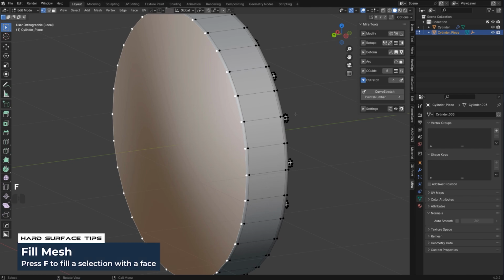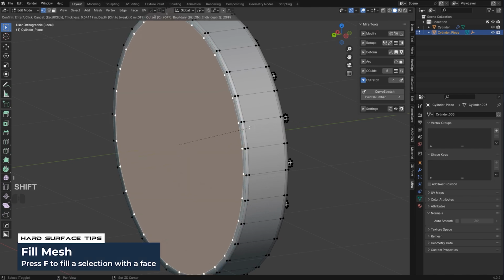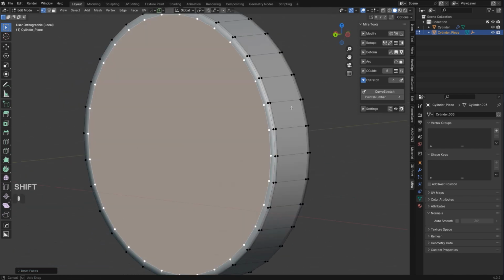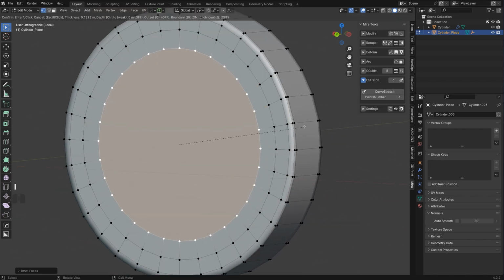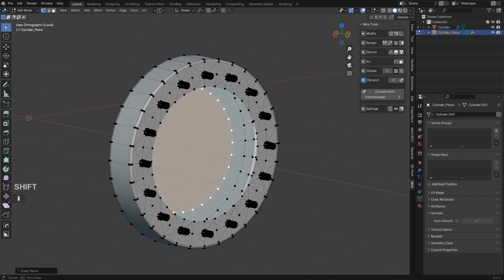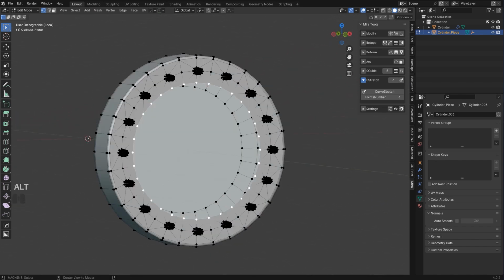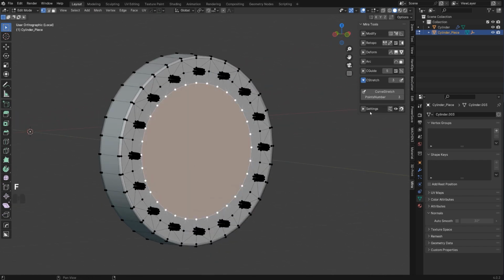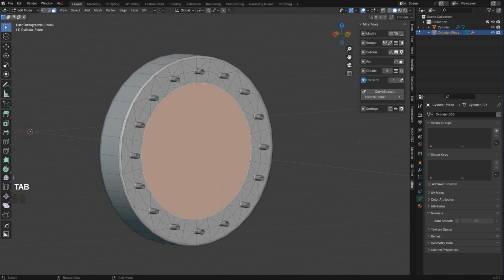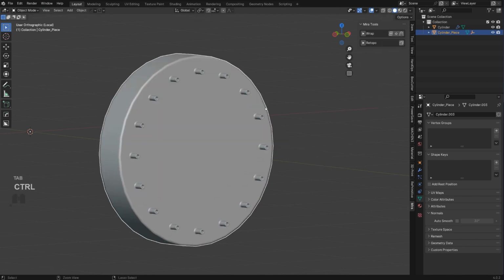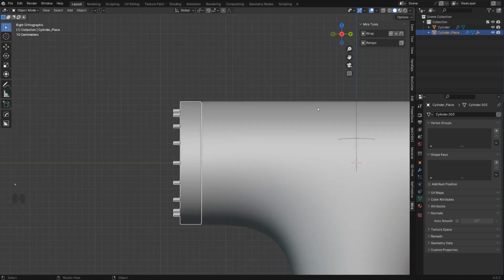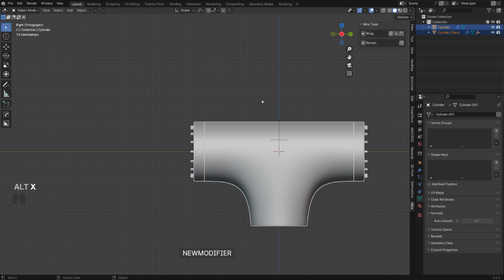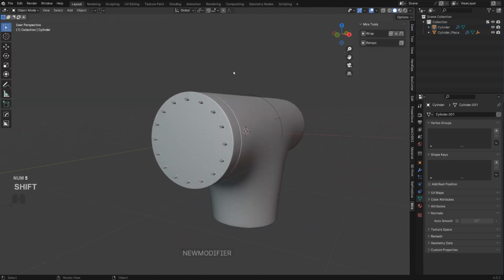So face, insert it just a little bit to create this kind of a really shallow bevel. Insert twice in here. We don't really need this face inside, but let's keep it. Here press F and insert it. So I to insert it, and Control 2, and we're gonna get a really clean subdivision. Boom, so that's an element. Then we're gonna mirror to the other side, and we're peachy.